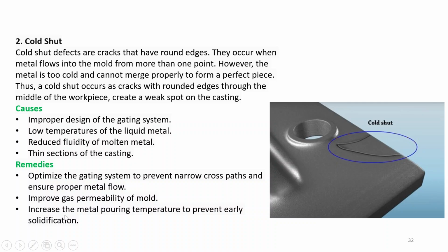Next is increase the metal pouring temperature to prevent early solidification.